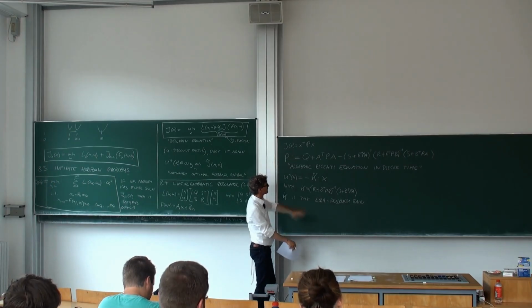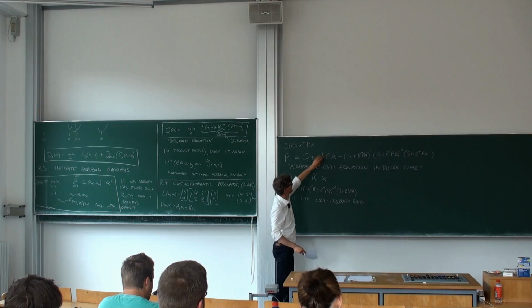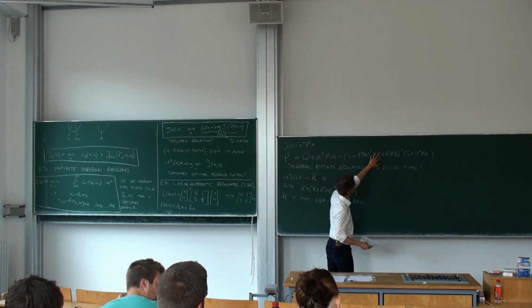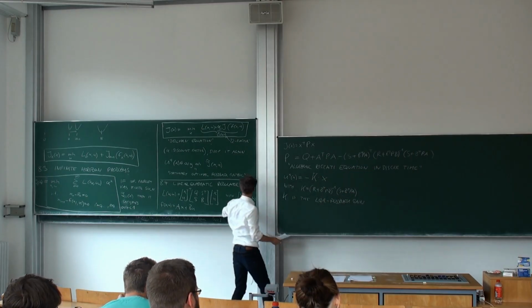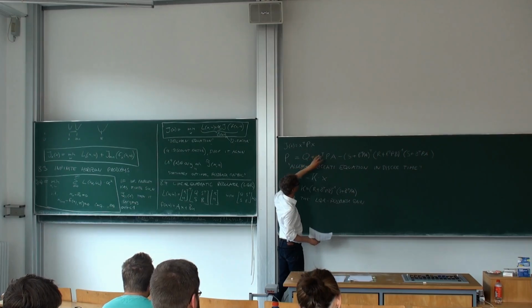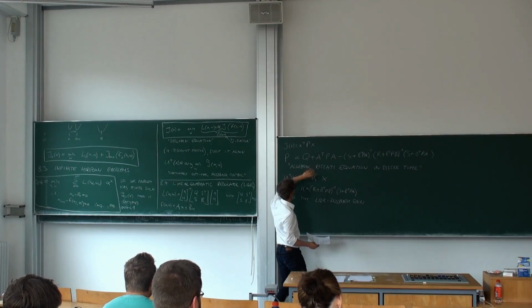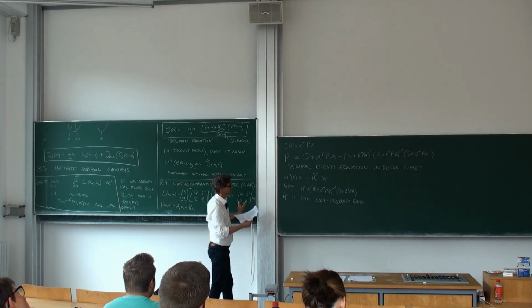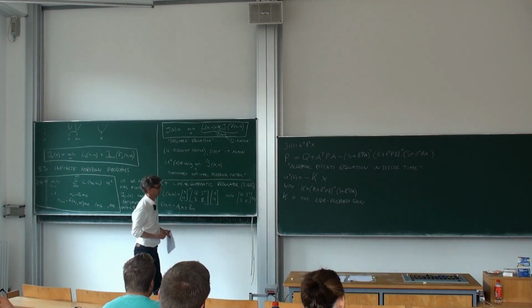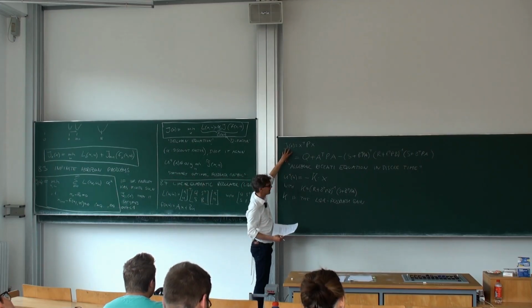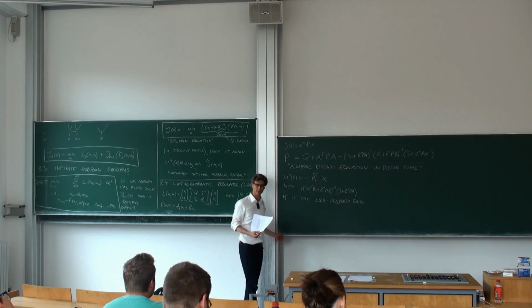So you basically start with an empty P, P 0. After the first iteration, you hopefully can invert that matrix, but that is assured due to positive definiteness, so it is well defined. The first iteration P would be 0, the second it would be Q, and then it would be a bit more complicated. After a while, it will be nearly the solution to that equation. So that would be one way. It's a safe way, but a very slowly converging way.